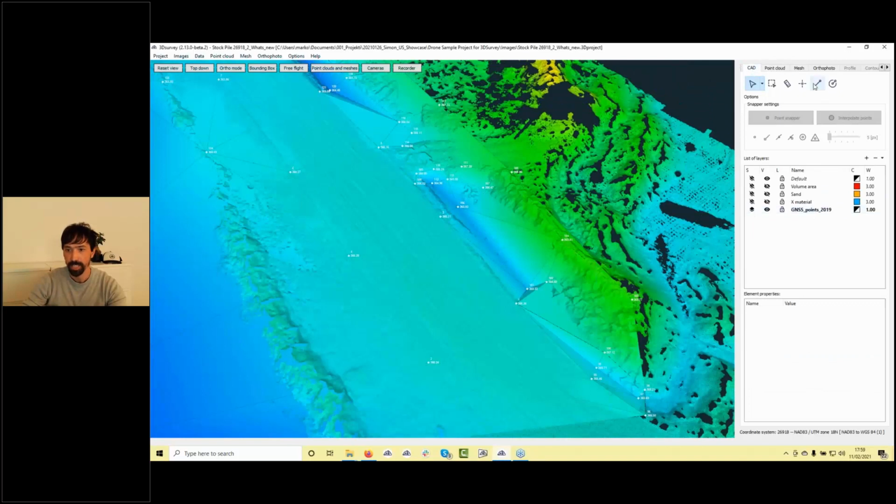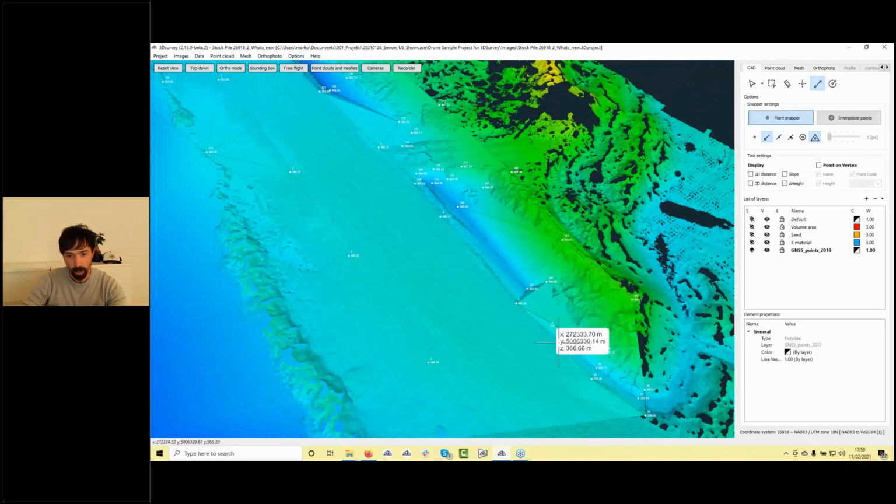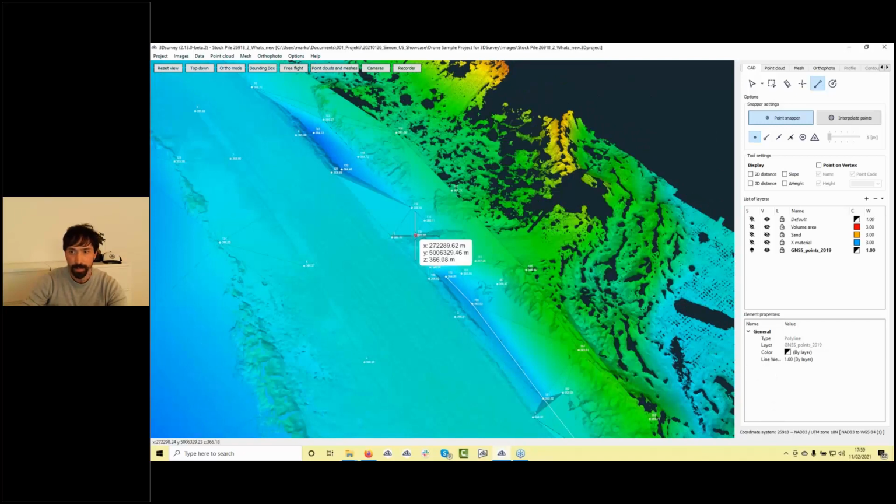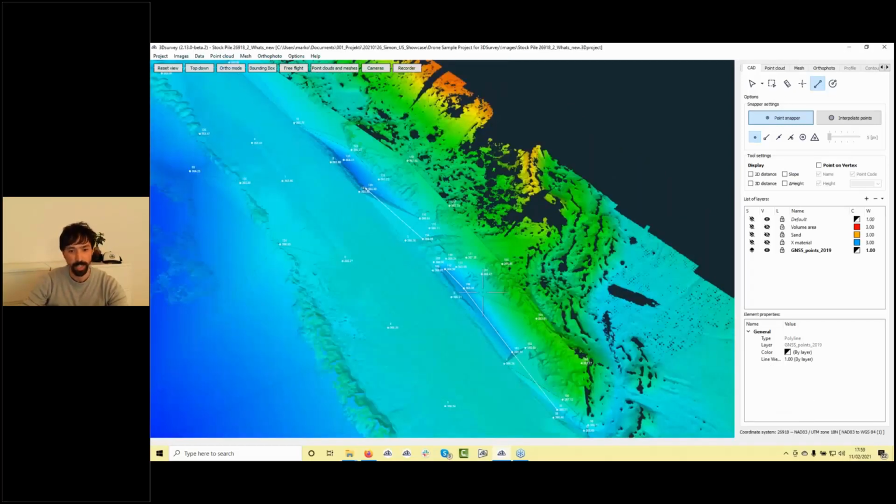Let's do in the same layer also some break lines. Snap to this point, at this point, because we see this is the bottom of this terrain, and also probably from this one. Oh, sorry, 2 lines. Okay, just to see the effect.